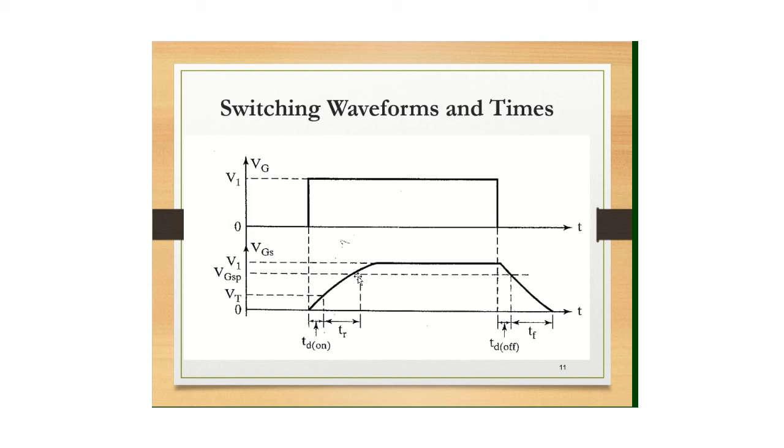So what is this voltage actually? It is nothing but the voltage required to drive the transistor into the linear region. Understand? That is the voltage required. So the summation of the two becomes our turn on time.